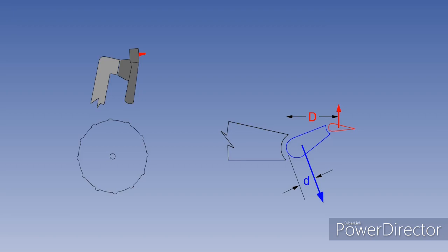Your flight instructors will teach you to put and then hold the aircraft in the required attitude using the flying controls. Only after you have achieved equilibrium should you use the trimming devices to reduce the stick force to zero. To fly the aircraft using the trim to change the attitude is bad practice.